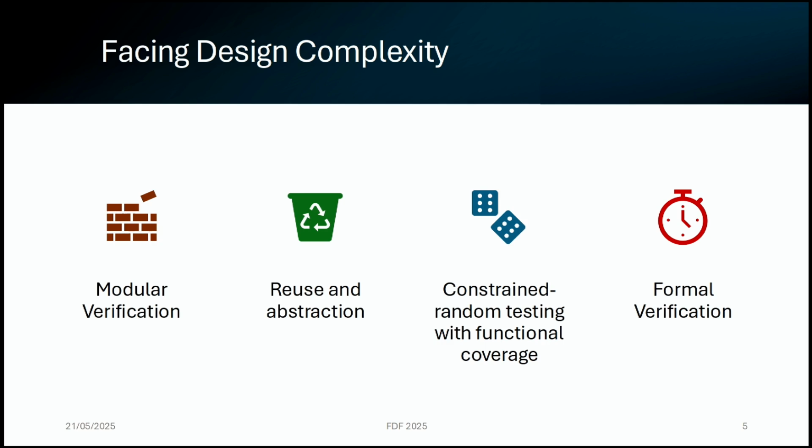For example, you might be writing some monitors, agents, let's call them, to look at the output of your design and some checkers to check the output of one of those subunits. Then that bit will go at higher verification level, and you will reuse it. And so you will have confidence that that part of your design is working both at unit level and at system level.